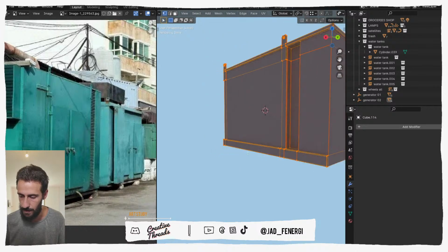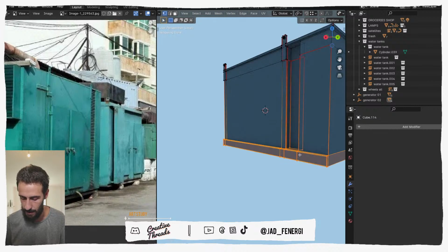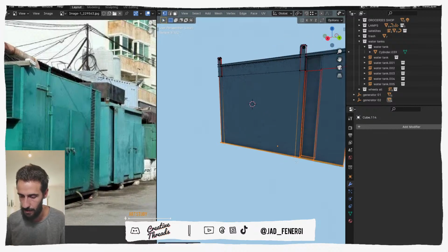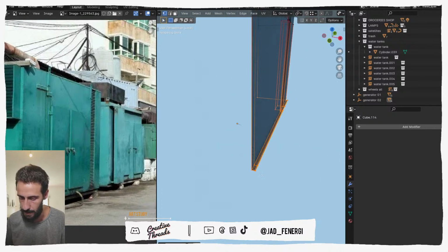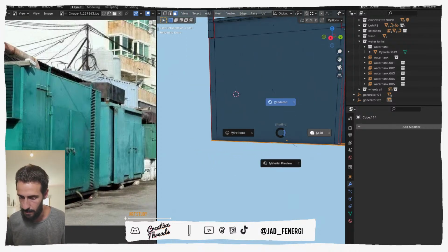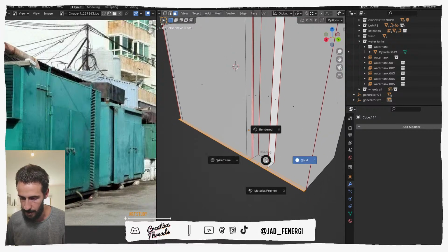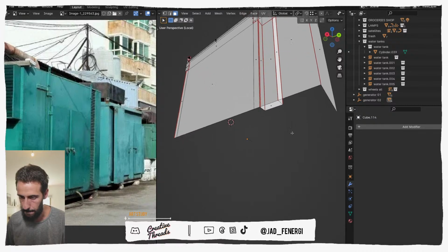and this is not that hard to do because what we can do is we can just, I think we can scale all of this on the Z and 0, so we can just collapse it and probably merge everything, so it will kill everything in here. And let's go back to solid, and since all of this is selected, we can just delete it like this.